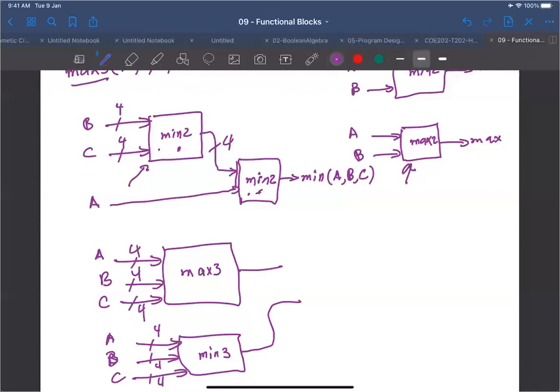It's a ripple carry adder, but you will complement the operand and add 1 from the carry in. Excellent. Yeah, this is a 4-bit adder, or you can say RCA as well.